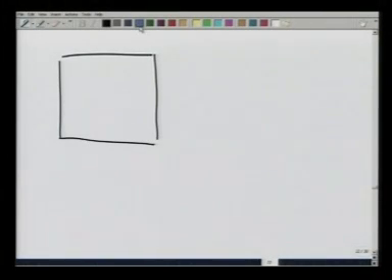I will leave a related problem for you, and that is in the same situation, if this tank is filled only up to 0.25 meters. In that case, I want you to calculate the force on A and the force at this wedge B holding the door. This will be slightly different from the problem that we just solved, because the surface of water is below this point and the loading is going to be triangular from this point onwards. I will leave it for you.